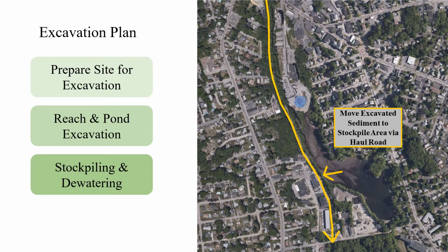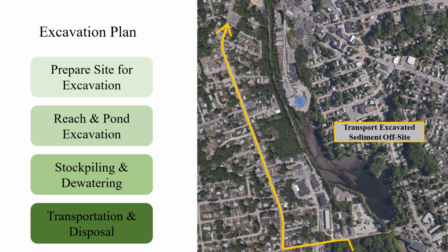Once excavated, the sediment will need to be stockpiled to passively reduce its water content. Because the sediment needs to have a minimum compressive strength for transport, some cement will also be added to the sediment. Finally, the sediment will be transported off-site. Sediment above the regulatory limit is considered hazardous waste and will be sent for incineration at $800 per ton, while sediment below the limit will be sent for disposal at a landfill at $70 per ton.